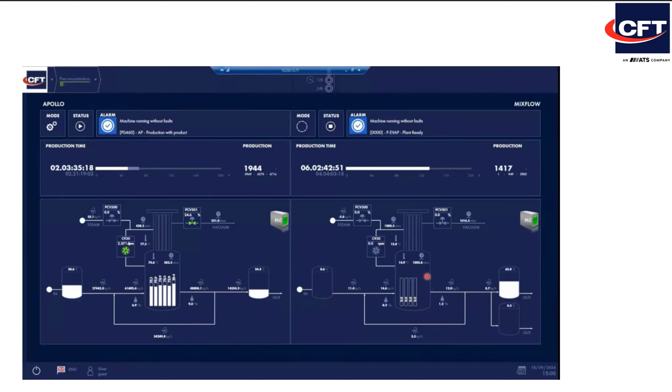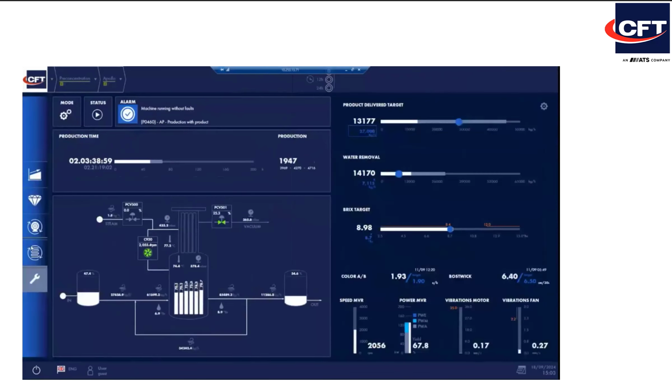The application is prepared to select, here on the top, other machines like the receiving, the hot break, the pulping and finishing, or the concentration and aseptic filling when they are present. What this screen shows is the operation mode, the prioritized alarms, and the situation of the anomalies. It also shows the main variables of the line, such as the compressor speed or the flows.